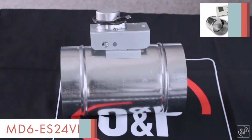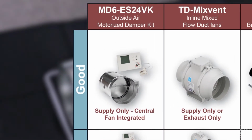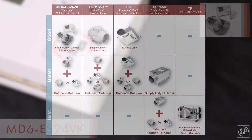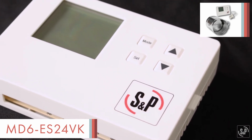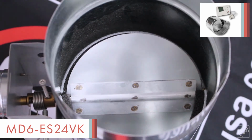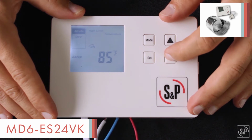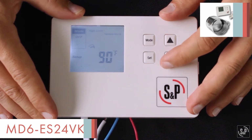The MD6 ES24BK kit combines our 6-inch round 24-volt motorized damper with our easy-to-use 24-volt EnviroSense ventilation control to provide a supply-only outside air solution that works with the existing air handler unit to introduce fresh air to the home. Program the control to open the damper and run the air handler for a set amount of time per hour to meet code. You even have the ability to limit operation based on high and low temperature and humidity settings to ensure that only temperate fresh air is supplied.